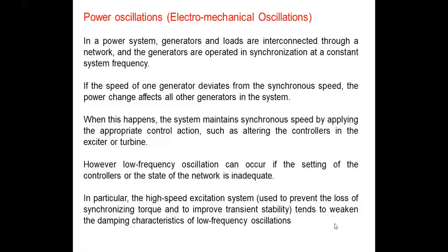These excitation systems can reduce the damping torque and thus the damping characteristics, resulting in low frequency oscillations, because low frequency oscillations are related to the damping torque. So this will again depend upon the operating conditions and the gain setting of these excitation systems.